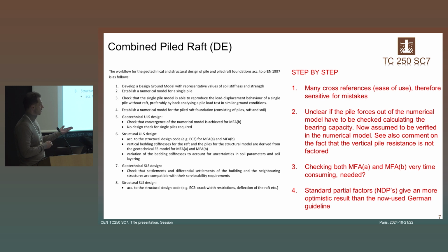Let's say in the model the pile has a bearing capacity of 800 kilonewtons, and if you would calculate it with a single pile method, you would get a lot less. You could raise questions about whether your model is then sufficient, but that is not particularly mentioned in the code.